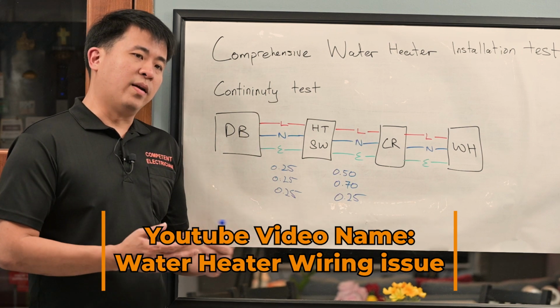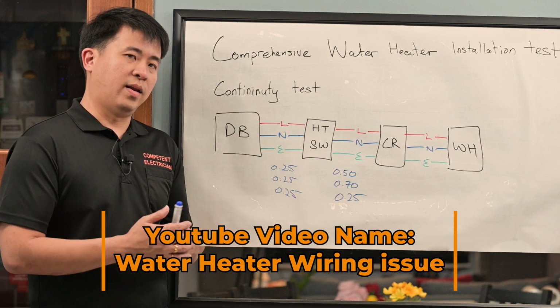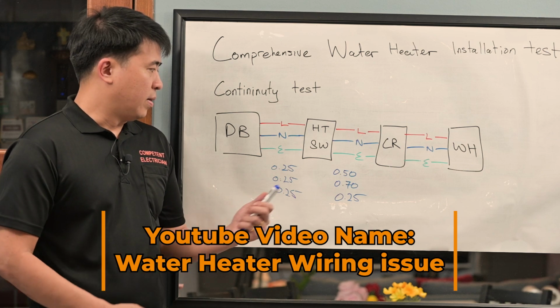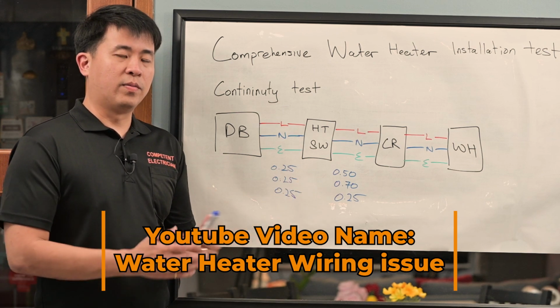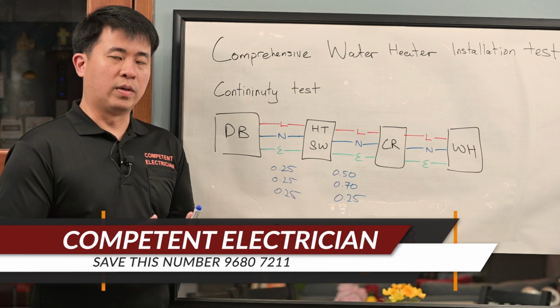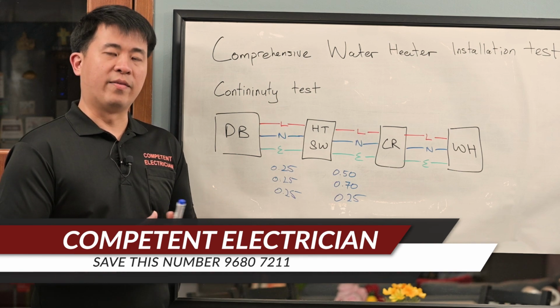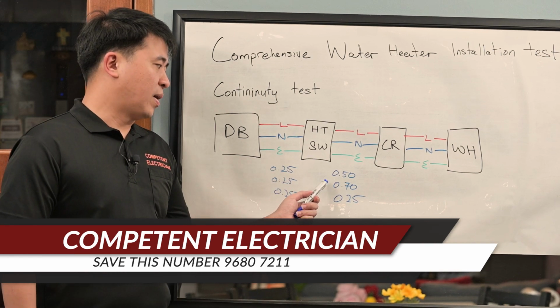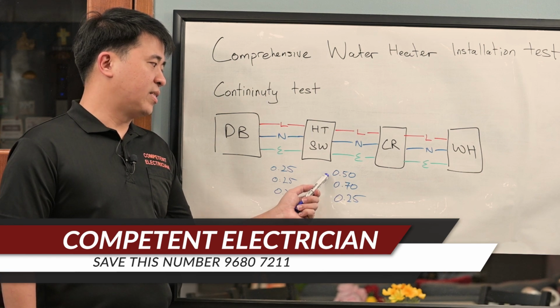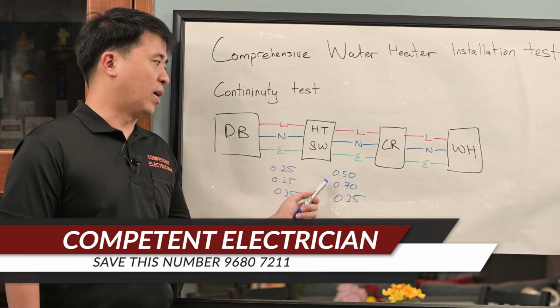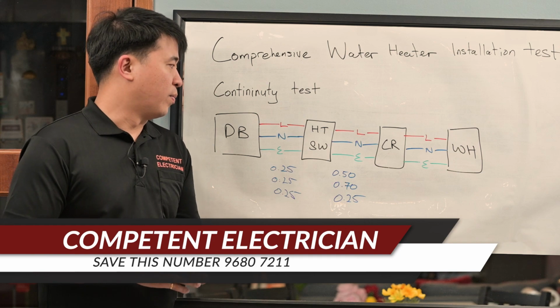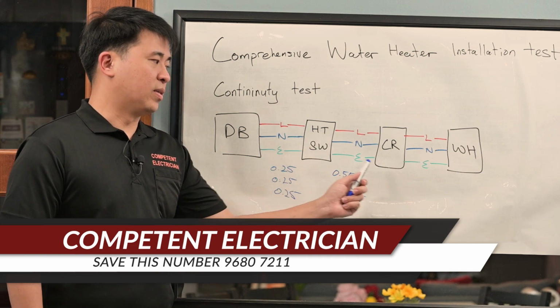As the years go by, the wire will go through wear and tear. The internal resistance of the wire may increase subject to the weather and the conditions they face. In a case that we found at a customer's house, there was a higher resistance between the live and neutral cable, between the heater switch and the ceiling rose.